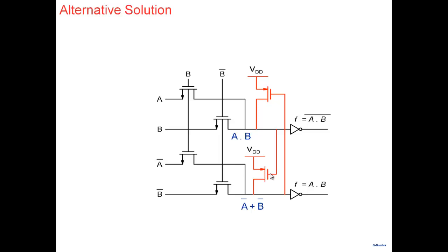So the idea is that you build a PMOS of actually very, very small size, because all that you're trying to do is pull it up enough so that this inverter works properly. You don't need a very strong PMOS here. All that you want is a minimum size PMOS that you can build and add this only at this particular point here.